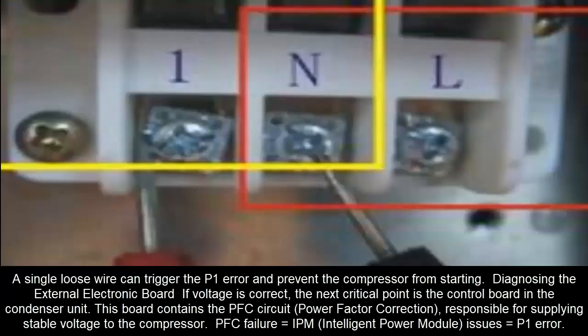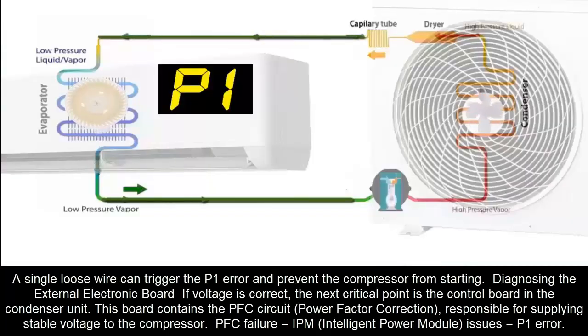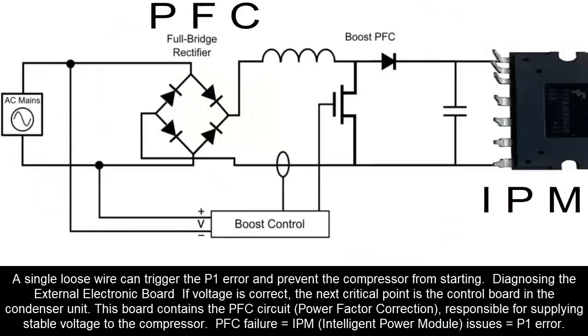Diagnosing the external electronic board. If voltage is correct, the next critical point is the control board in the condenser unit. This board contains the PFC circuit, power factor correction, responsible for supplying stable voltage to the compressor. PFC failure equals IPM intelligent power module issues equals P1 error.